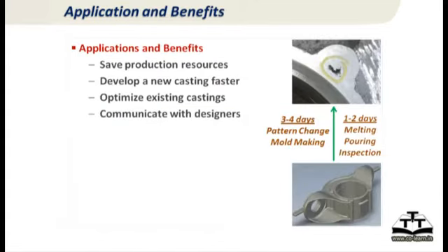So just a quick example here. If you look at this part, and then you have a real shop floor experiment done, and then you find there is a porosity there, but you really don't know what could have caused the porosity or shrinkage porosity. So you could have saved production resources by actually doing it by simulation. Suppose you want to develop a new casting without trials on the shop floor, can you do that? Yes, we can do simulation and maybe do just one trial run on the shop floor to verify the simulation is right. You can improve your yield, reduce your cost.